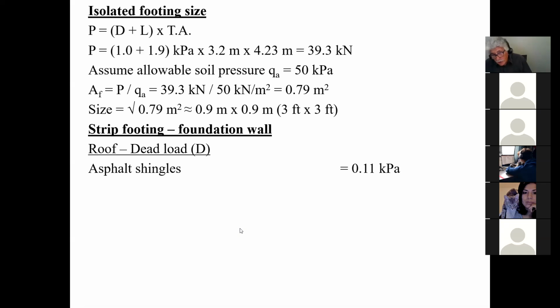Okay, so you guys learned how to inspect a roof. Great. What I'm saying is that there's a roofing unit that you guys might not be aware of. It's called a square. In roofing, a square measures 10 feet by 10 feet. That's 100 square feet for a roofer. For example, they'll say your roof is about 20 squares. That means it's 2,000 square feet.